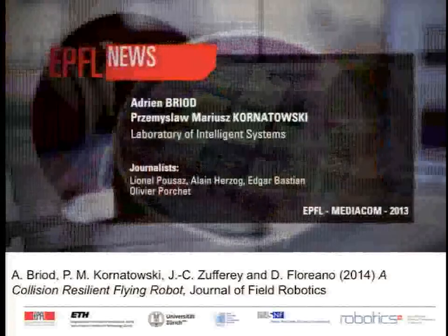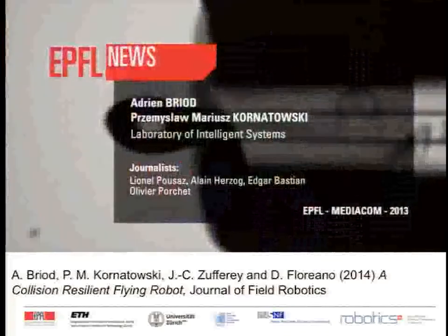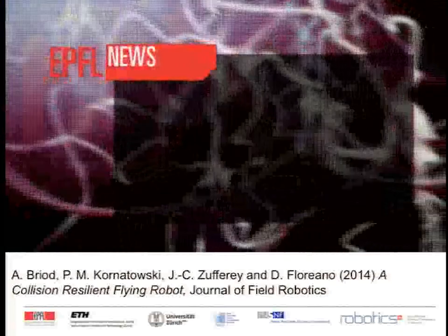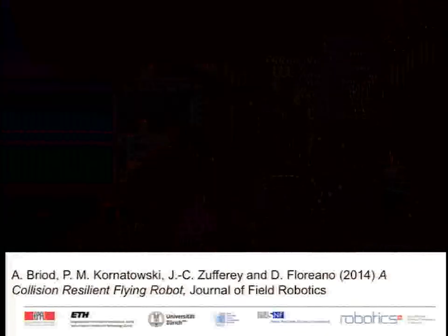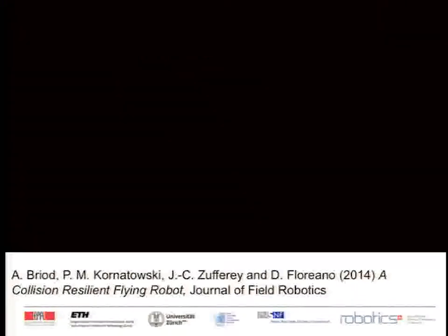So what you see here is another example of what I call this principle of adaptive morphology. You can either add actuators and motors to your robot and display multiple modes of locomotion, and that's okay. But then your cost of transportation will be quite high in all of these modes. Or you can change the morphology of the robot. You can either do it dynamically or change the way in which you conceive the robot so that you decrease the cost of transportation in both locomotion modes.